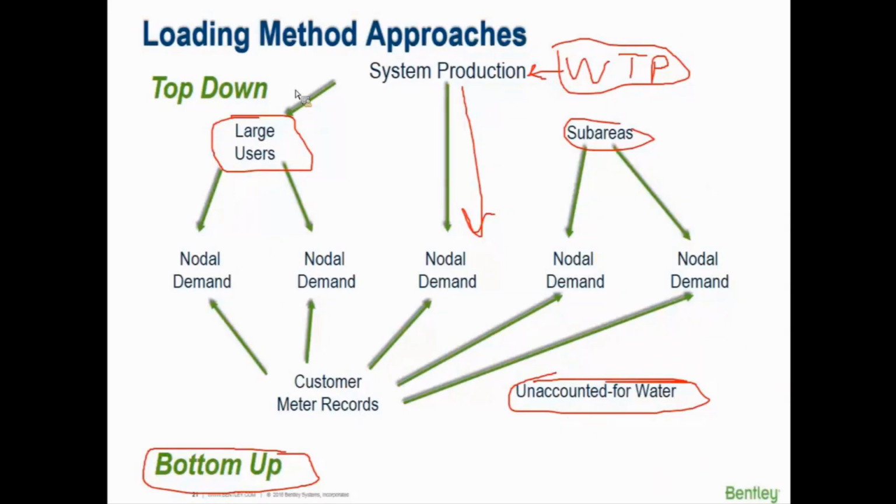This may begin to look more like a mass balance. In situations where systems are so big and the water loss is so high, there's an approach of dialing down the pressure at night to minimize water loss. Because the less pressure behind the orifice, wherever those leaks are, the less water that's lost. And then during the day when people need the water or to put out a fire or something, pressures increase. Yes, you lose more water at that point, but at least it's not happening during night.